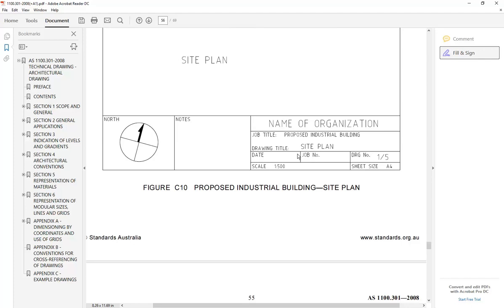So the project, of course. On every page, you should have the name of the project. And then on every page, you need the name of the sheet, the date, scale, sheet size is a good one. It's not always there, but I think that's a really good thing to have. Who it's drawn by, is that on here actually?